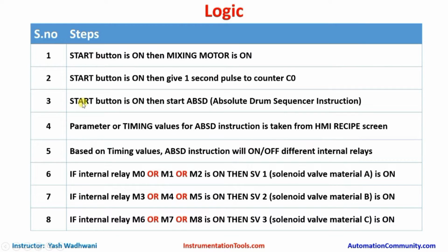So here are the first 3 steps. When the start button is pressed, these 3 things must happen. What are these things? First of all, as soon as the start button is pressed, the mixing motor should start, or be on. It will always be on when the start button is pressed. After that, as soon as the start button is pressed, 1-second pulses will be given to the counter using a special register of the Delta PLC. So the counter value will increase.